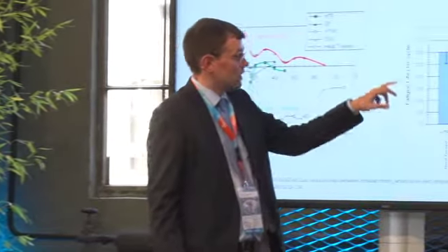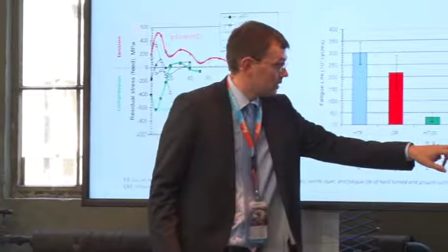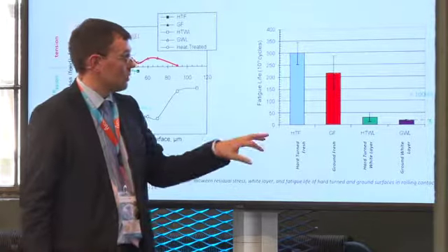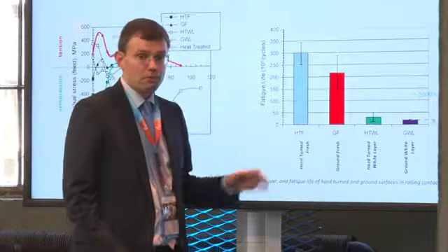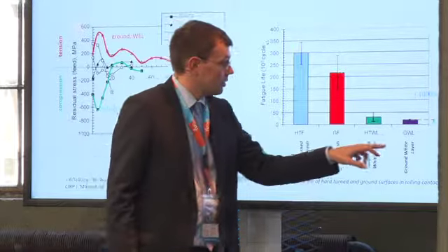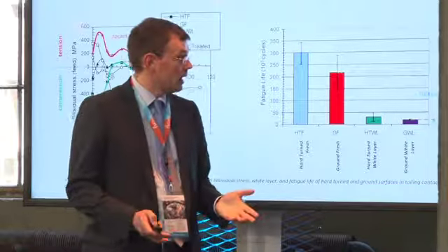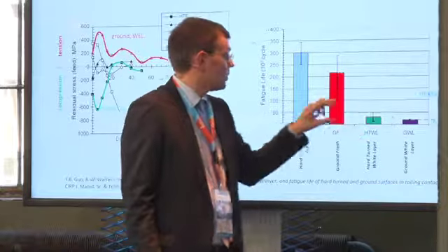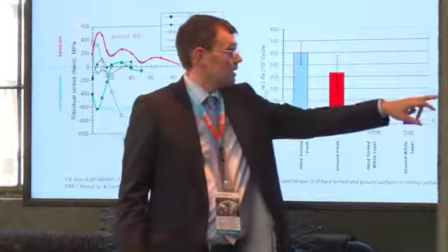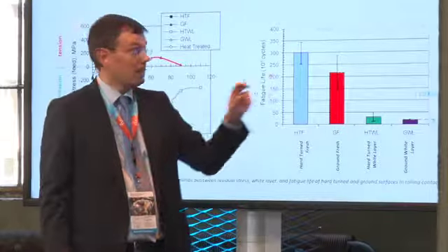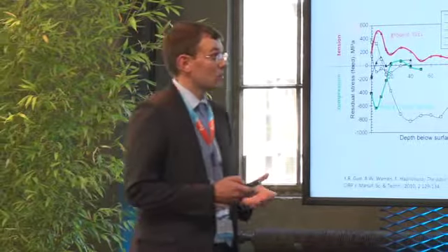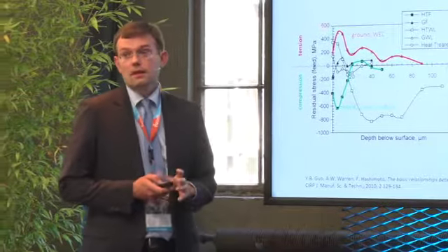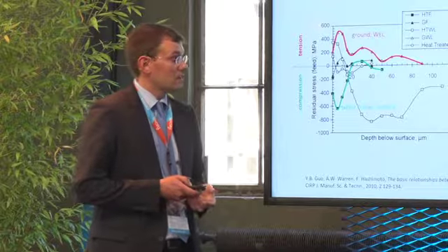If you look to the fatigue life for these four methods, and I'm again not going into too much detail, the difference between milling in a proper way and grinding in, I would say, an aggressive way, the difference between both processes in terms of lifetime can be 1400%. And again, this is not about small values or exact values, but the order of magnitude is very significant. And that means that there is a lot to gain, I think, in this field.